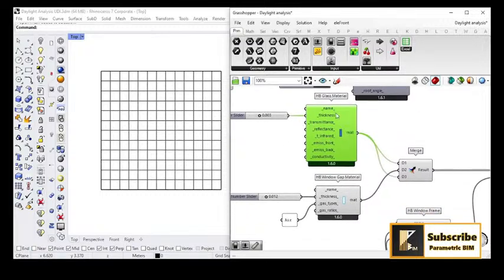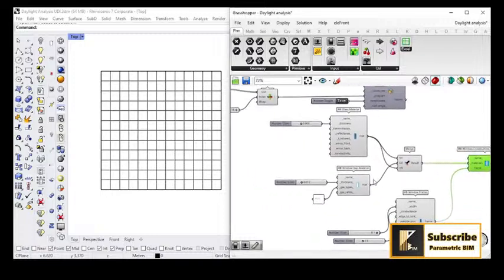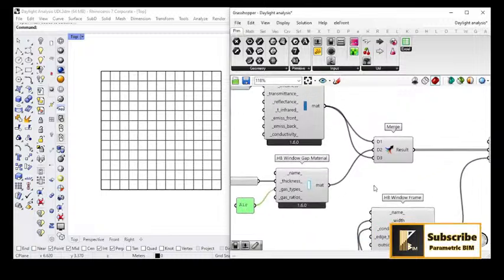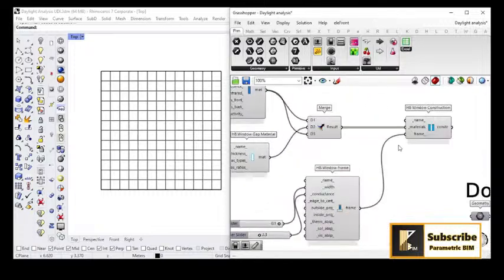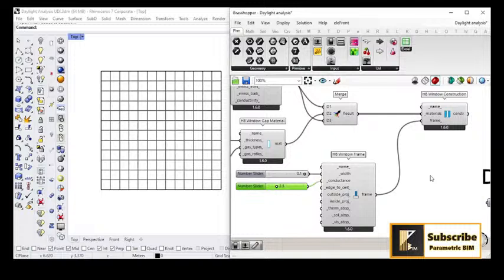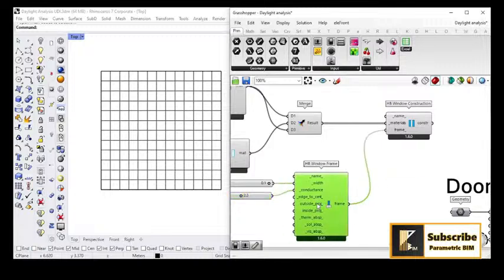For example, here I have a double material, so I assigned a honeybee glass material with a thickness to the window construction, honeybee window construction, and then I put a gap with air with a thickness here in between, and then also the frame I give some properties for the frame, for example the width, the conductance, and you can also give some properties for the outside projection, the thermal absorption, the visual absorption, the solar absorption, and so on.